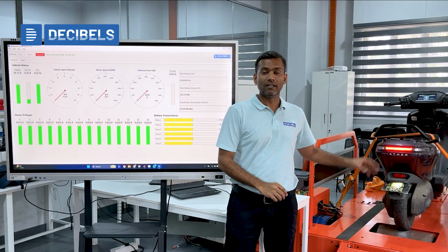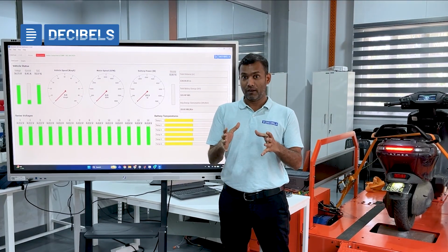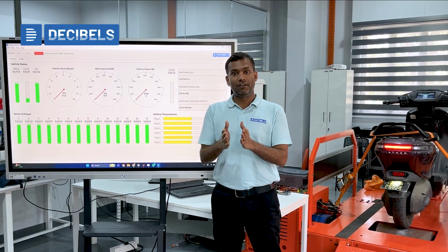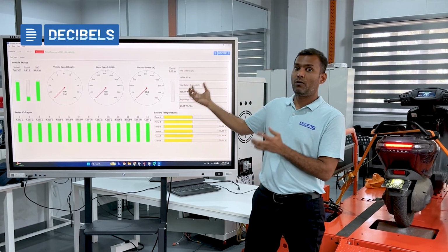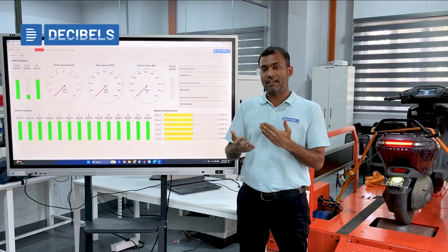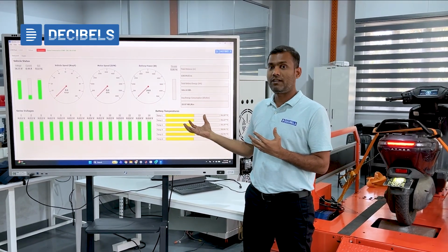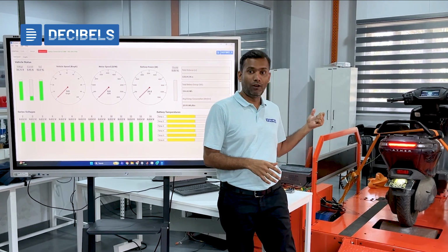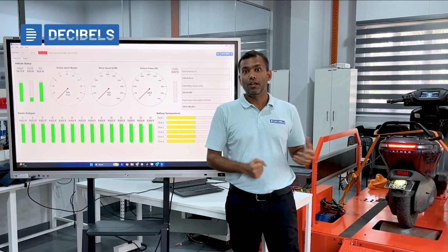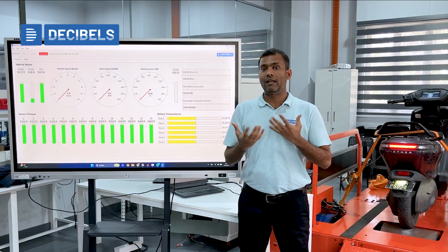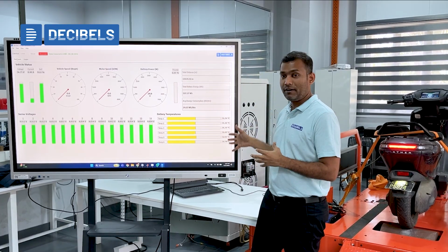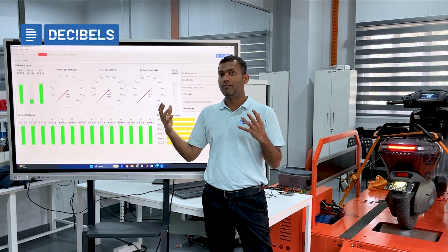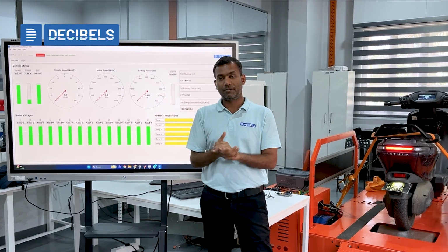And the opportunity for the third case is that now you have all the vehicle parameters and then you have the vehicle. Let's say you develop a digital twin of an electric vehicle or the digital twin of the battery, and you want to validate your digital twin, right? So here is the data from the testing and a variety of testing cases, and you can use the data for verification and validation of your digital twins. Apart from it, because you keep collecting a lot of data from the vehicle, you could work on developing AI and ML models to predict, let's say, the battery temperature or degradation of the battery. A variety of those things can also be useful in your scope of research activities.